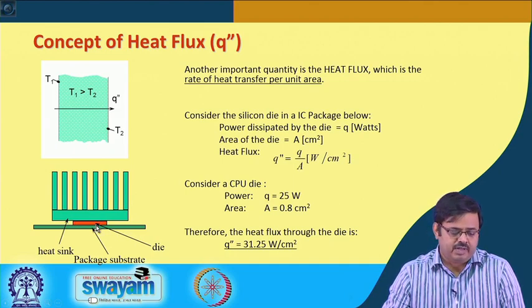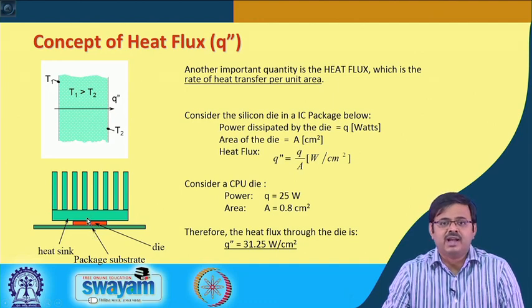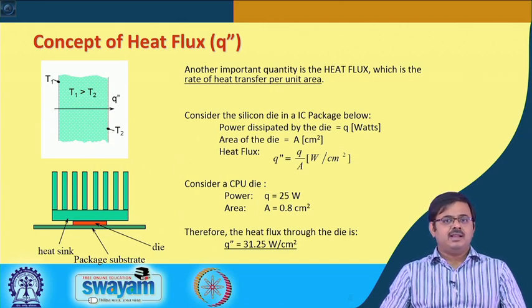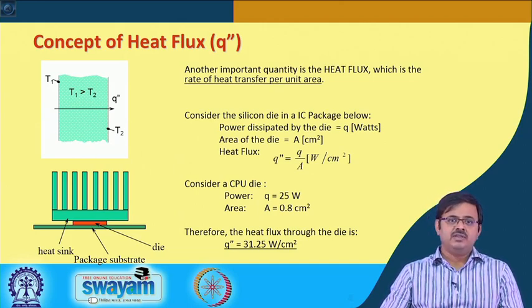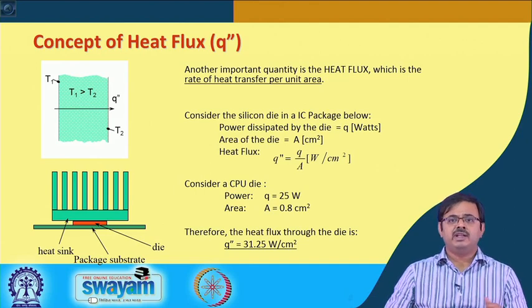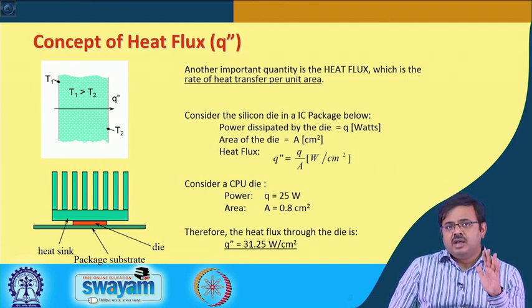So, this is a CPU or a die as we are calling it, this is the substrate, and on top of that I have put something called a heat sink. People with a mechanical engineering background who have done heat transfer will definitely recognize what a heat sink is. This is a finned heat sink with parallel plate fins, and the whole idea is we use finned heat sinks to have more surface area and therefore more heat transfer. We will talk about finned heat sinks in great detail later, but think about it,